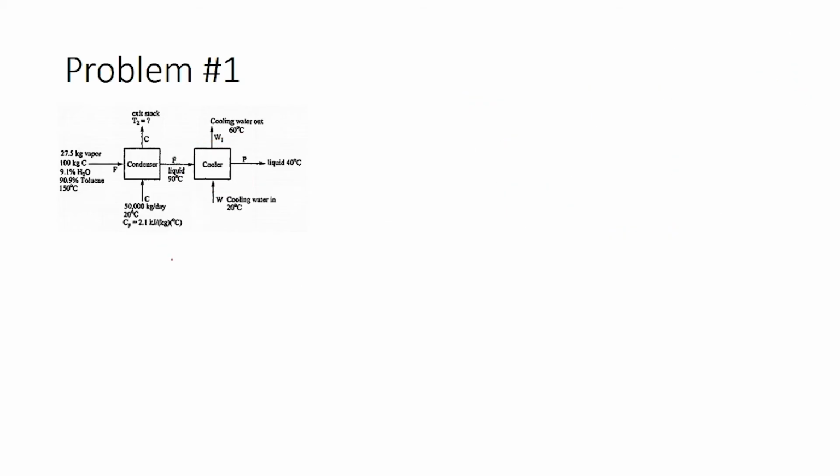So, now we can calculate H3 cap. H3 cap is for the process where water liquid at the reference state of 90 degrees Celsius is being cooled to the water liquid which is leaving through the product stream P at 40 degrees Celsius. So, the process is the integral from 90 to 40 of Cp of water dT. You have cooling from 90 degrees, the reference state, to 40, the exit condition for water. So, this would be 4.2 times 40 minus 90, giving you a value for H3 as minus 210 kilojoules per kilogram.